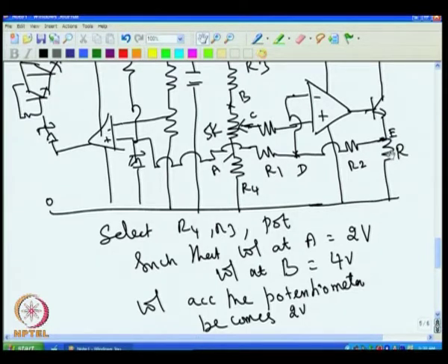So, what can actually be done now is, since we have taken a 5 volt Zener, if I make R1 and R2 equal, then I will get 2.5. Instead of 4 milliampere, we need almost about 1 milliampere current, almost negligible current. I can make sure that A is also kept at, say, 2.5 volt.